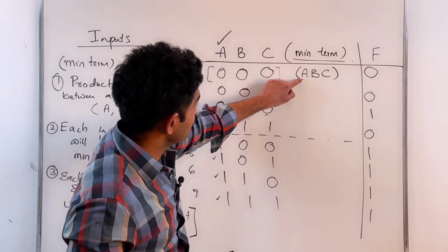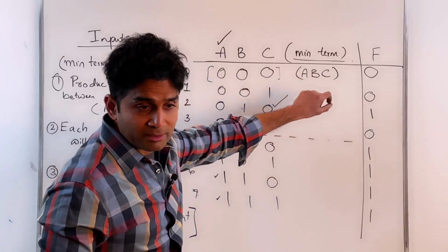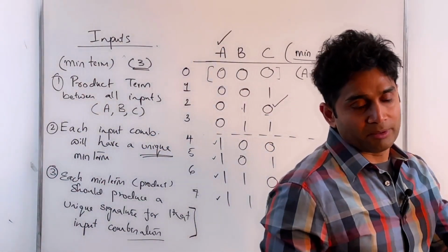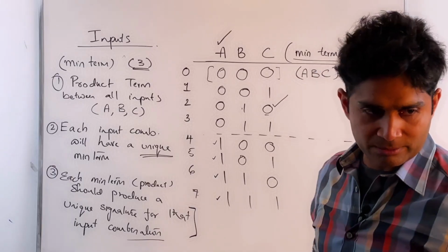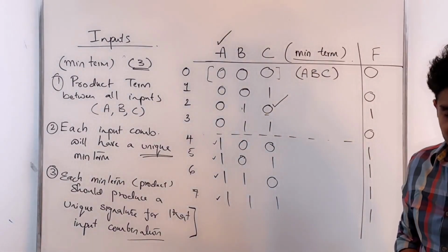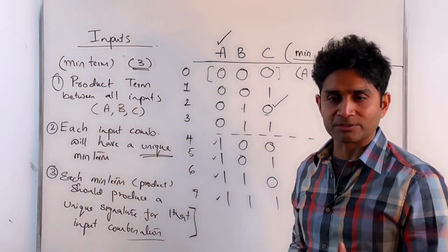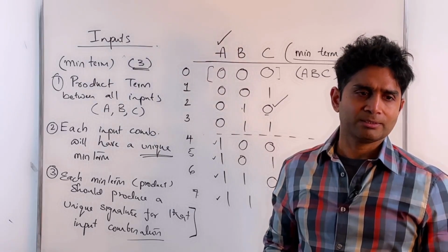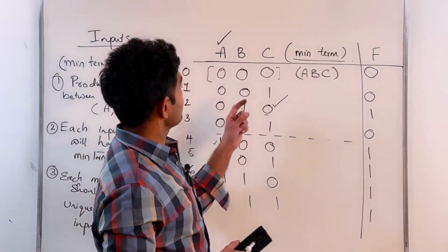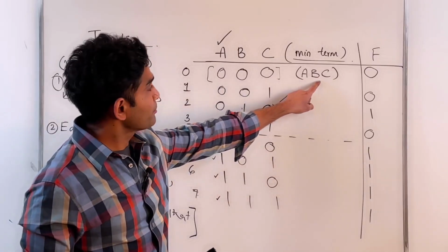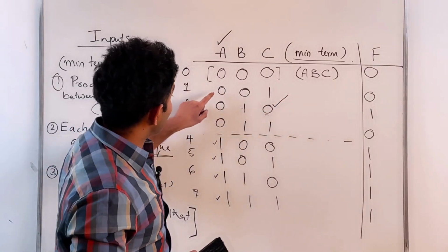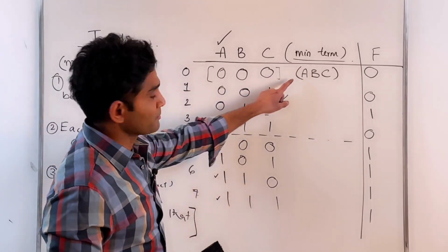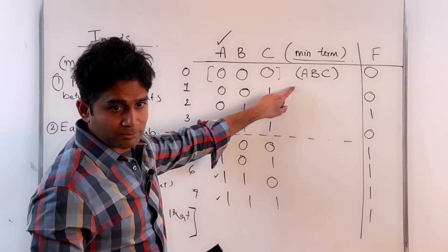That's A and B and C, right? For an AND gate, if I have all zeros, or in fact even one input that is a 0, the output of the AND gate is 0. It's an AND operation, very similar to your product operation. X times 0 is 0. So in this case, that gives me 0. What about if I plug in these values into this minterm? What do I get? A 0.